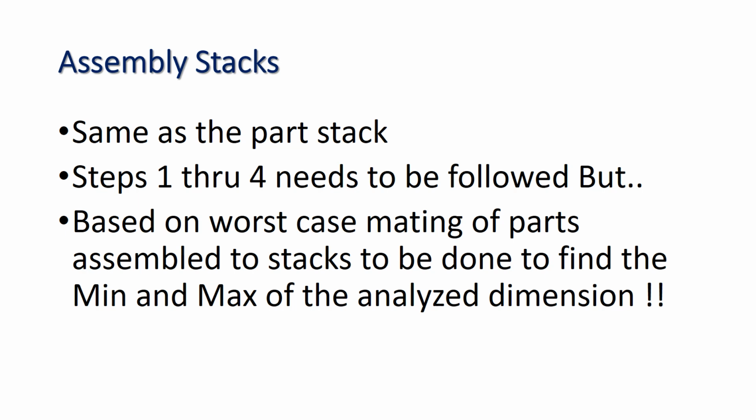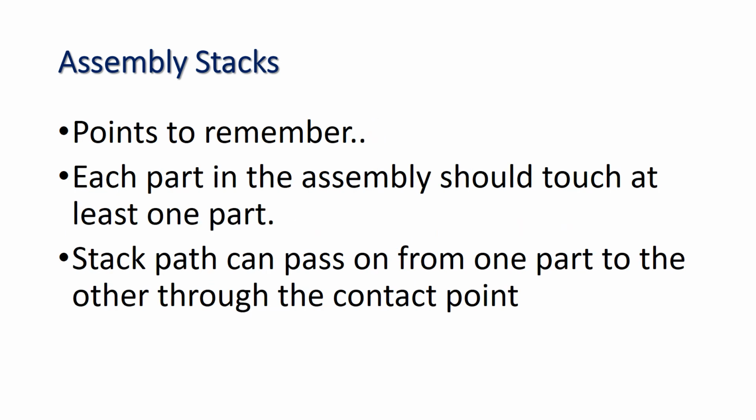Part stack steps 1 through 4 need to be followed, but based on the worst case meeting of parts, assembly stacks are to be done to find the maximum and minimum of the analyzed dimensions. Points to remember in assembly stacks: each part in the assembly should touch at least one part. The stack path can pass from one part to the other through the contact point. Note this: each part should touch at least one part.